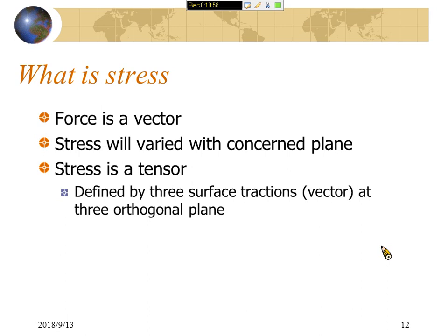Stress and strain are tensors with rank 2. So you will have 9 components for stress and for strain. Of course, only 6 components are independent, because the stress tensor and the strain tensor are symmetrical. They are symmetrical tensors with rank 2. So in total you have only 6 independent components of the stress tensor and strain tensor. Okay?